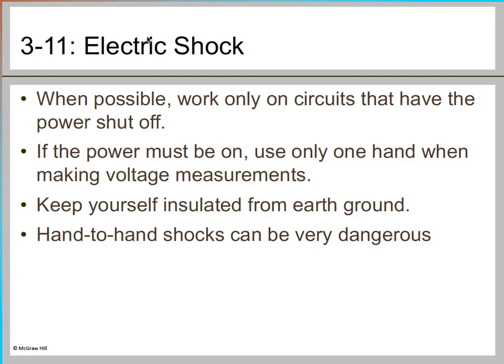When you build the circuit, your power must be shut off, and once the circuit is completed, only then should you start doing the measurement. When you are measuring the voltage, it is advisable to measure it with one hand. Otherwise, the high voltage can get into your body.